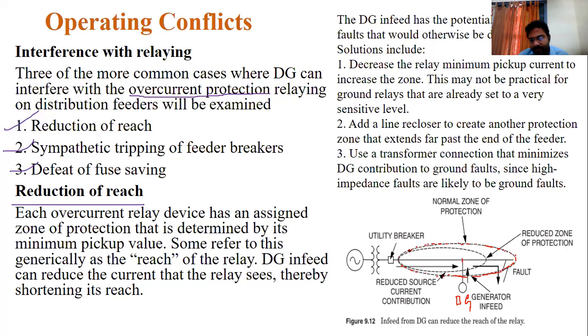If any fault occurs in this area, the relay detects that fault and gives the command to the circuit breaker, and the circuit breaker operates. Remember, in this covered area, within these red lines, if any type of fault occurs because of a short circuit and all other things, the relay senses it and gives the instruction to the circuit breaker.